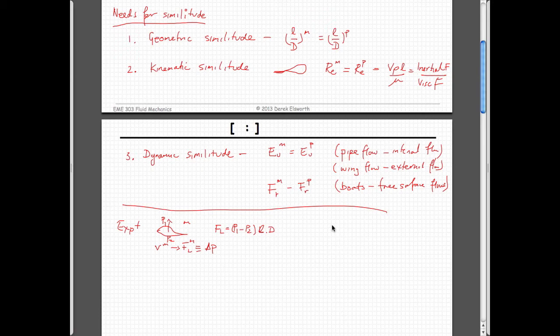And what you could do is plot that data point for a particular velocity in terms of this figure, which would be a Reynolds number: the velocity you're flying at, the density of the fluid, which is air, times a characteristic dimension of your wing, which is length, divided by the viscosity of the fluid, whatever that is. So you do your experiment at 1 meter a second, say, and you'd have one data point at this particular Reynolds number.